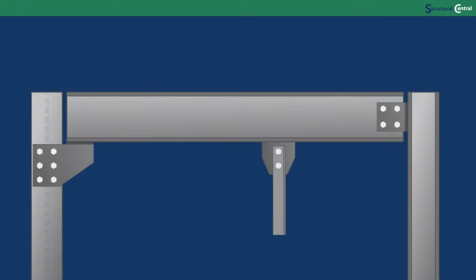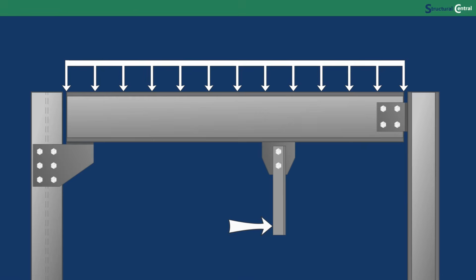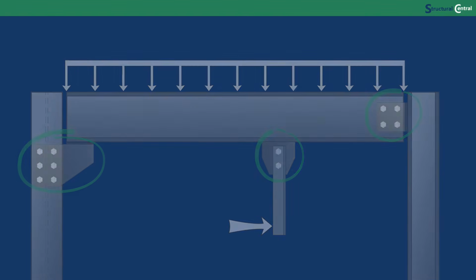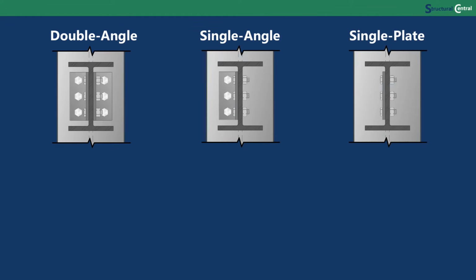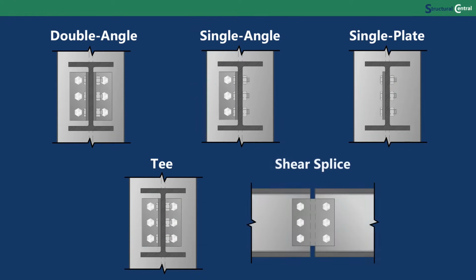Eccentric loading of bolt groups comes up frequently in steel connection design. There are the obvious cases where the connections are being designed for moment, like for a bracket plate or for a hanger that has a lateral load. But also many shear connections for simply supported beams are required to consider eccentricity in their bolt groups. Eccentricity may be required for double angle, single plate, and T connections, as well as for shear splices.